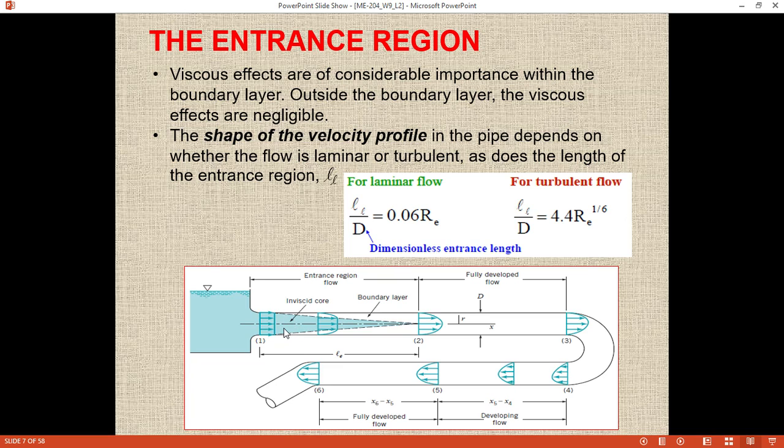You know the width of your car, and based on that you must know what the width of the core should be to test the car, and what the diameter of the pipe should be to achieve that width of the core and length of the inviscid core. So this is a very important application of the inviscid core that you must keep in your mind, okay.